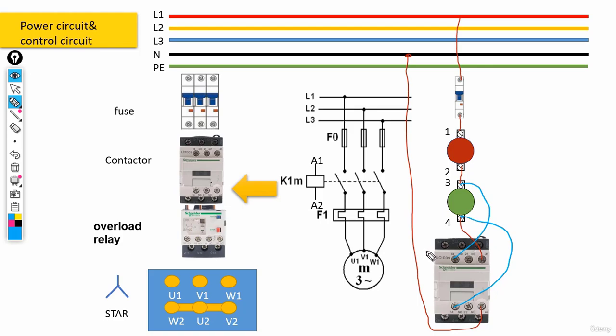Now, if we go ahead and start pushing this button down, the contactor obviously starts working, but this time there's a difference. These two contacts, 13 and 14, would start working as well. Alright? And when we stop pushing it, when we pull our finger up, the electrical current will go through a path like this.